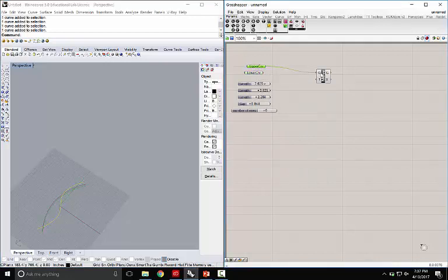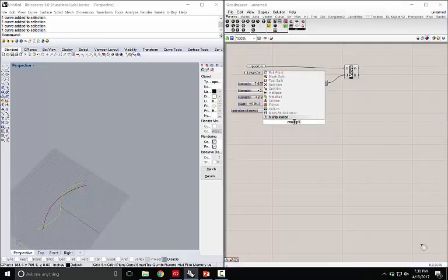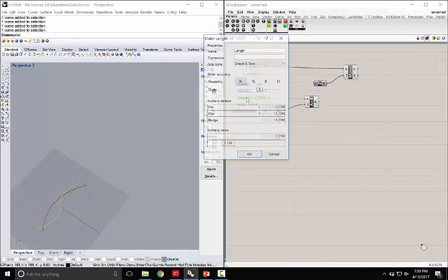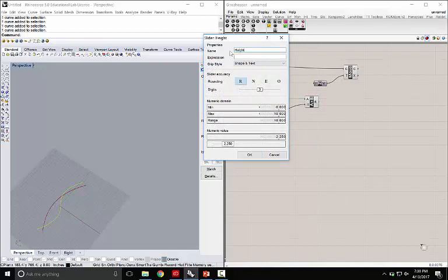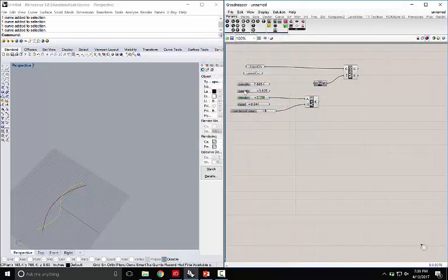The upper curve, we're going to move up in the Z direction, so I need a Z component for translating it. And the value that we're going to translate it up in the Z direction will be a multiplication. So I'm going to put in a multiplication component. It's going to be the number of rows times the height of the brick, which was this 2 1/4. I need to go back and change these names. Height and width. And then that multiplied value goes into the Z.